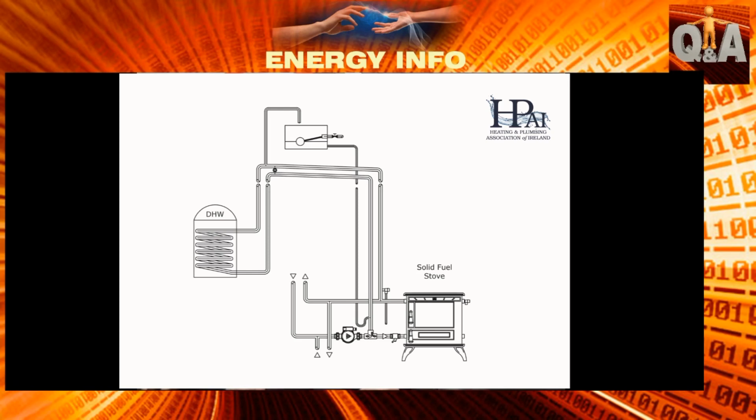Again, you see there's an injector in front of the pump doing the same job. You also see with solid fuel it's very important to have a safety valve as close as possible to the appliance. I'm inclined to think a safety valve should be on the neutral point of the system, on the neutral circuit, and not on the pumped circuit, as it's just less likely to pick up any debris or whatever like that that might cause an obstruction.